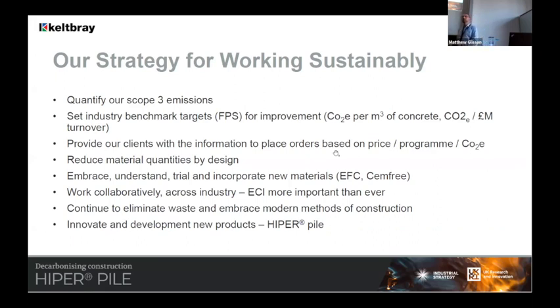To give you an idea, earth-friendly concrete is a zero ordinary Portland cement-based concrete, so it's an alkali-activated concrete mixture. I think there's been some presentations here today talking about the heavy use of OPC. There's zero OPC. It's around about 340 kgs per meter cube of secondary cementitious material, comprising GGBS and PFA with a strong alkali activator. Normally when you get down to a CEM3C type mix, the 5 to 10% of OPC is acting as your activator. We've got rid of that activator and replaced it with a strong alkali instead.